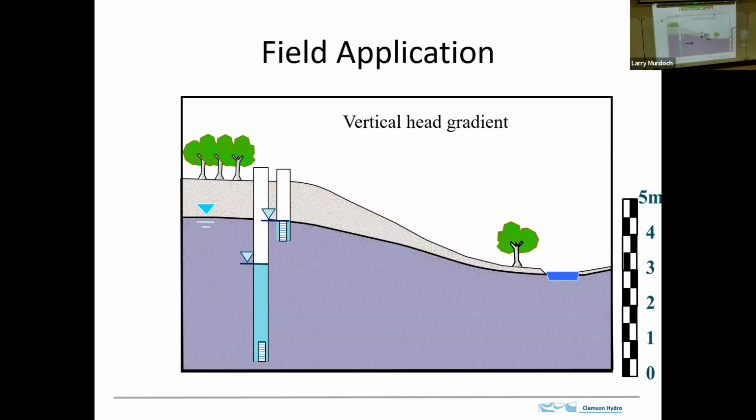And we can also do this in the vertical direction. And this is where it becomes important to recognize that this hydraulic head, 3.2, applies here. See the little dashes? That's what we'll see later is a well screen. Those are small slits in this pipe that allow water to flow through and connect this tube, this piezometer, with the aquifer. So the hydraulic head is 3.2 there.